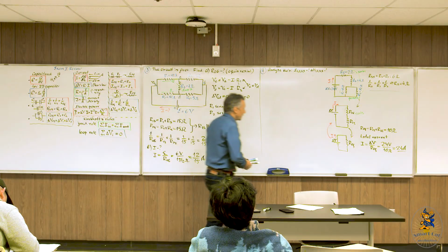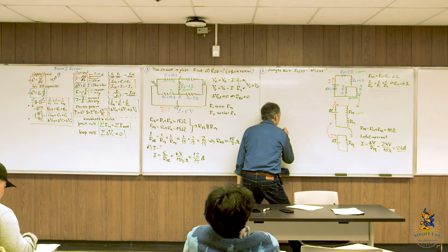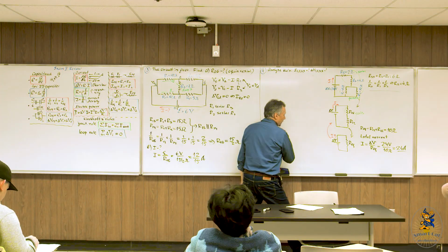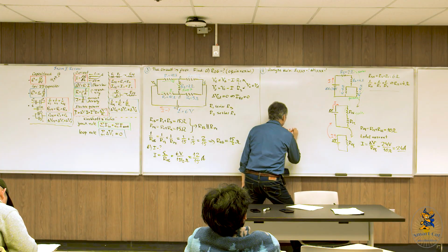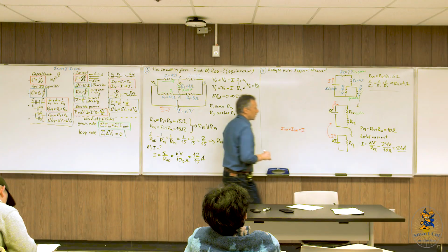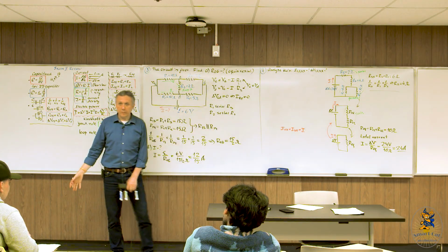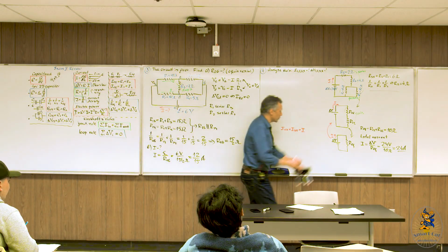You should be able to identify them on the formula sheet. All right. So it means that I can write I12 equals I35 and equals our total current, which is the equivalent current through the equivalent resistor. And it is equal to 2.4 amps.